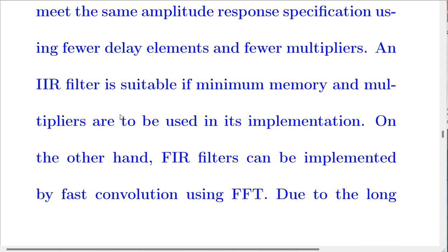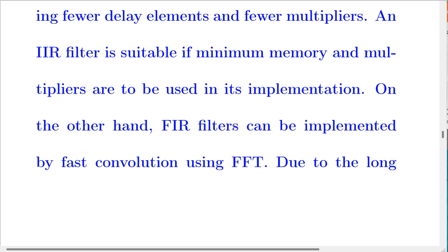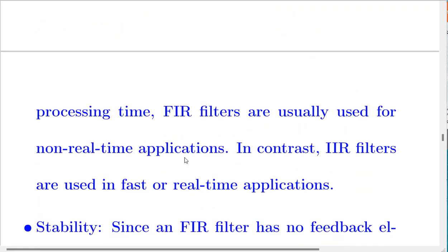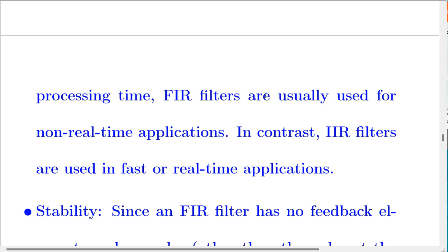Okay? On the other hand, FIR filters can be implemented by fast convolution using FFT. Due to the long processing time, FIR filters are usually used for non-real-time applications, meaning offline processing. In contrast, IIR filters are used in fast or real-time applications. That's very important.